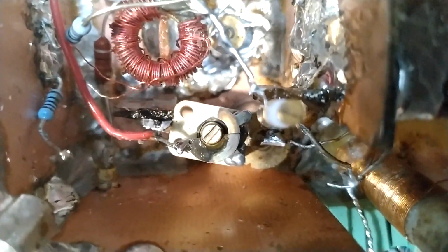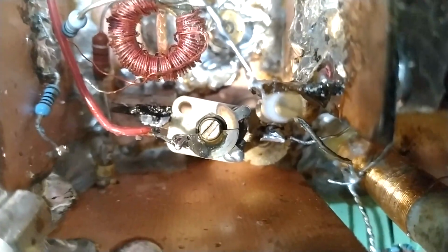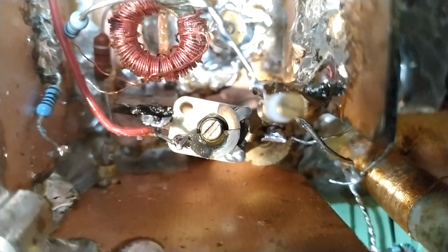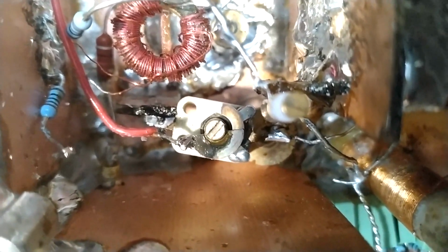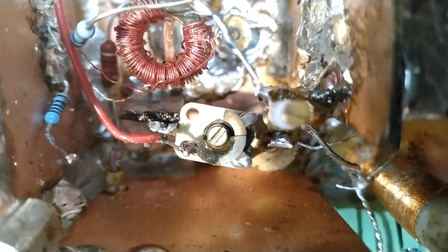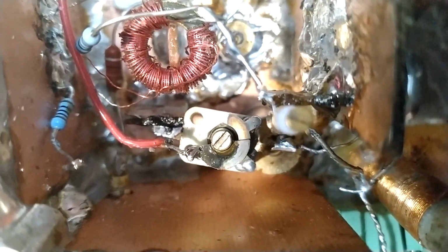That did not solve the problem, so now I have soldered a wire directly on the movable part of the capacitor, so the contact resistance is no longer involved. I have a soldering on both halves of the tunable capacitor, and the wire can move a little up and down, and that doesn't matter.